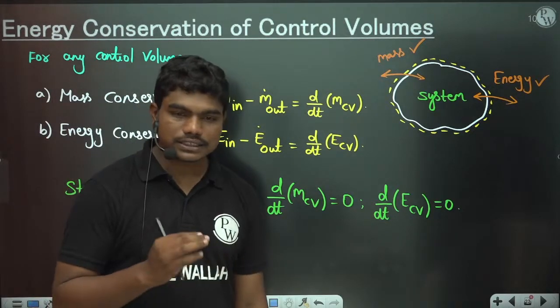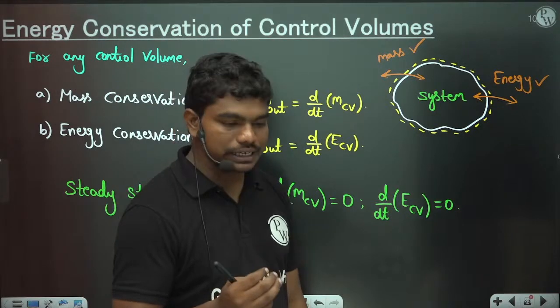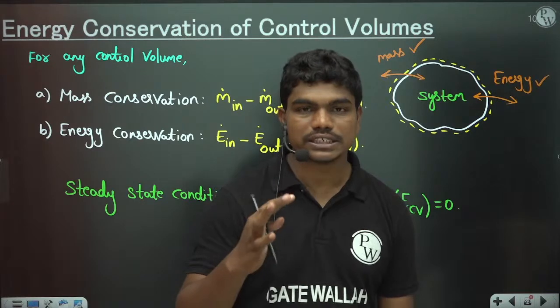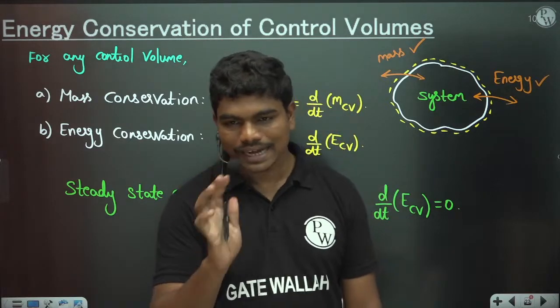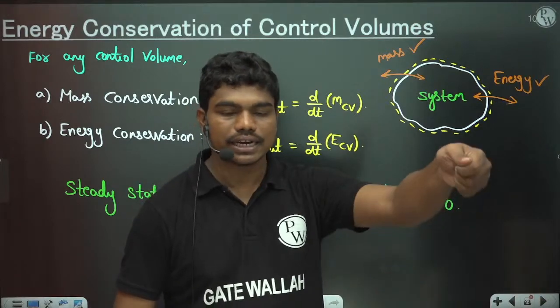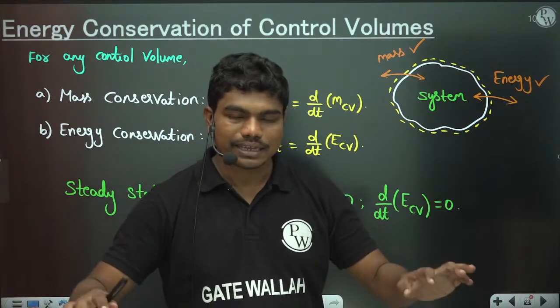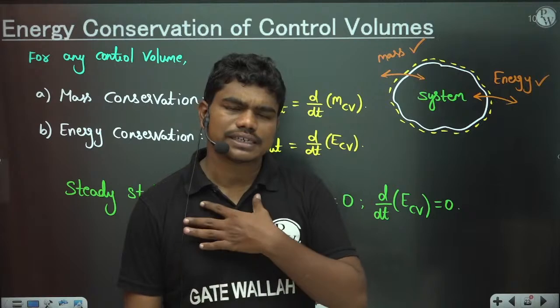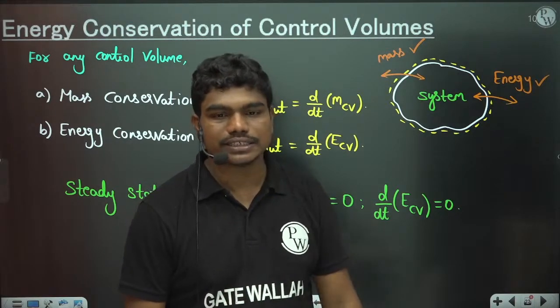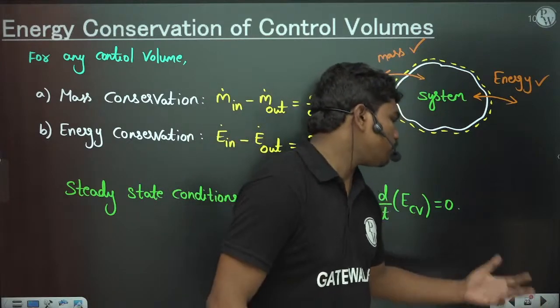Now why are these steady state conditions very important? We also deal with the steady flow energy equations. Why are steady flow conditions very important? Because practically all devices operate under steady conditions, except in the beginning, when starting the device, and when stopping the equipment. Apart from these two stages, for 99% of the lifetime of equipment, it runs in steady state conditions. Why does this happen?